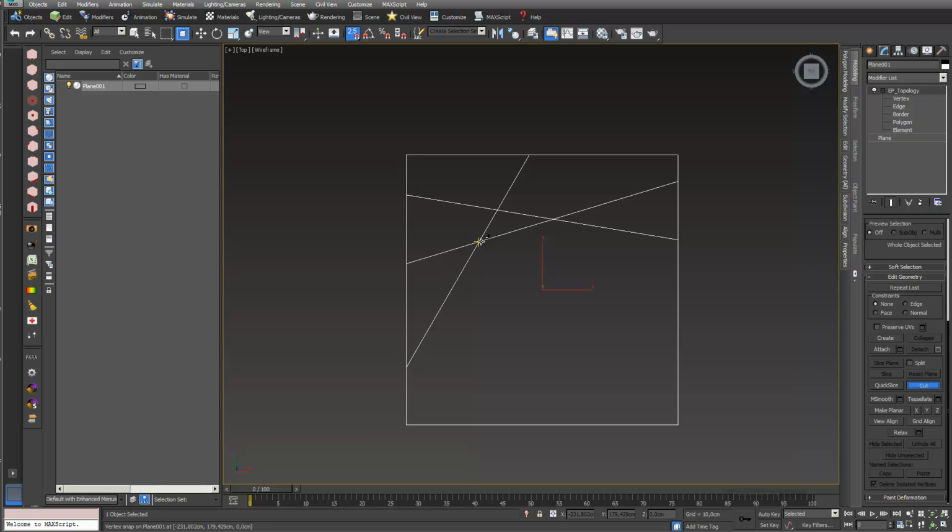If I use the cut function, I can snap to vertex points, something like this, and I go to my edge, and with right mouse click I stop, otherwise I continue cutting. Right mouse click I stop, and so I can define areas a little bit like this. Right mouse click I stop it, and you can see that I just follow, and right mouse click stop. And I think this snap function only makes sense with vertex. So that's a way of how to create a basic topology, and like I already said, it could also be a pattern. Okay, right mouse click, and I leave my cut function.